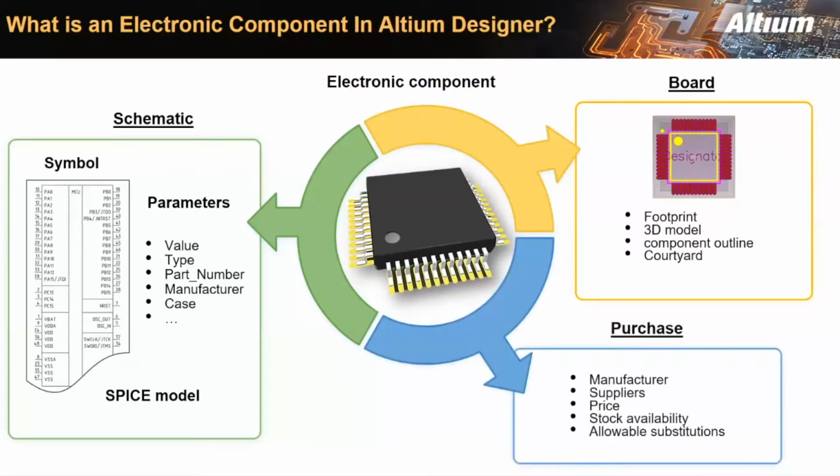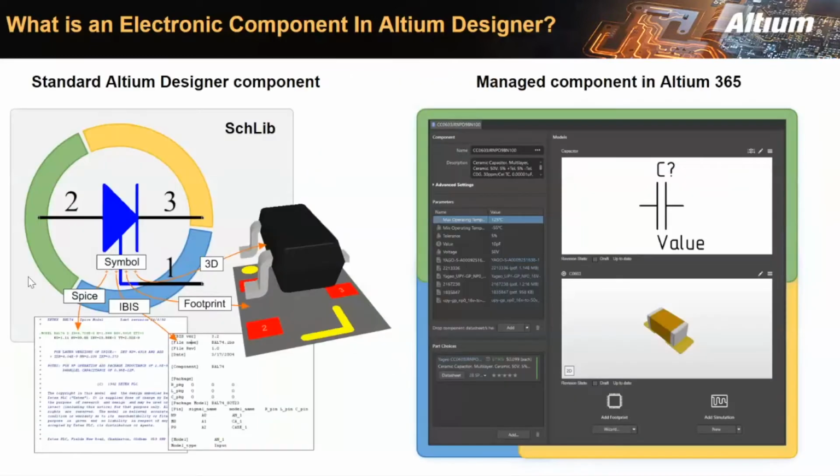Parts procurement can occur anytime after the completion and approval of the schematic design and move in parallel with the board design. For procurement, the name of the component and the manufacturer are important. Also, you need to know which supplier sells them, what their cost is, whether they have them in stock, and whether they are still in production. The component impacts many aspects of the design.